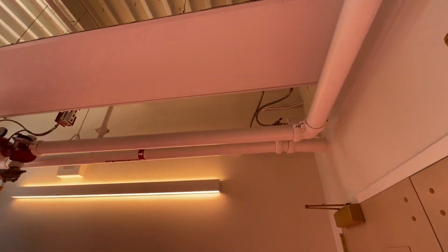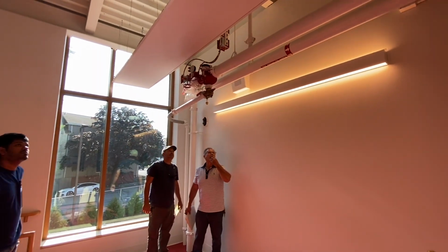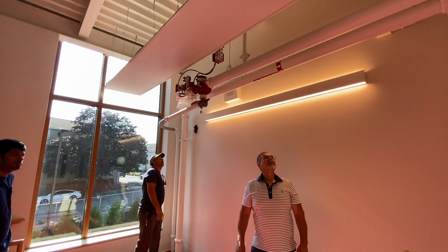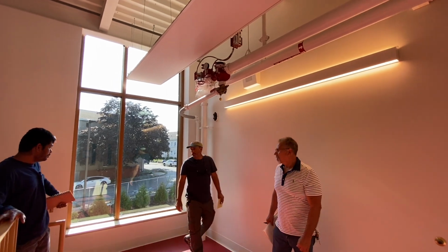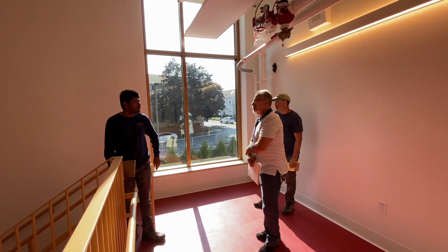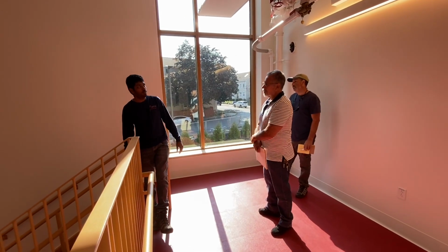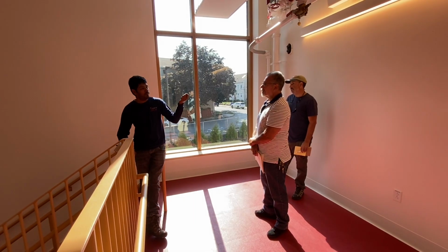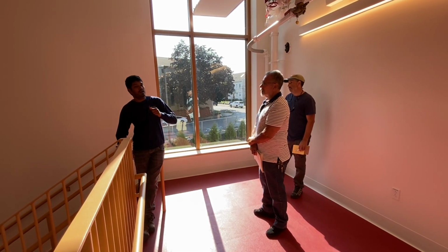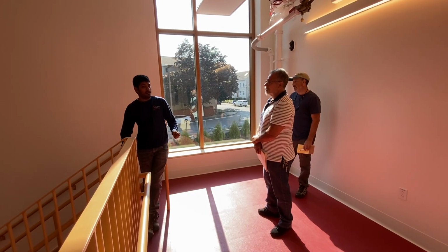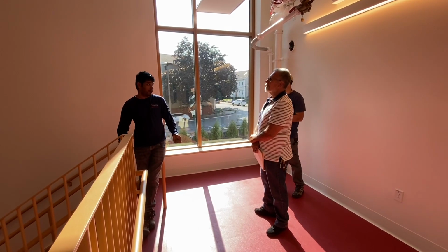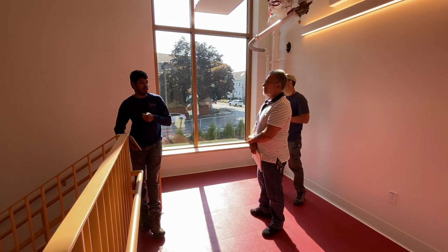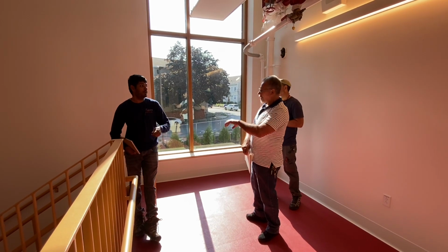So they get the zone valve, sends it in and out. And we have two methods to maintain the DP on the water loop. Normally we vary the pump speed to maintain the DP. We also maintain the DP if the pump is already at minimum but my DP is still higher. Then I modulate the DP through my bypass valve as well. That is also controllable and modulating.